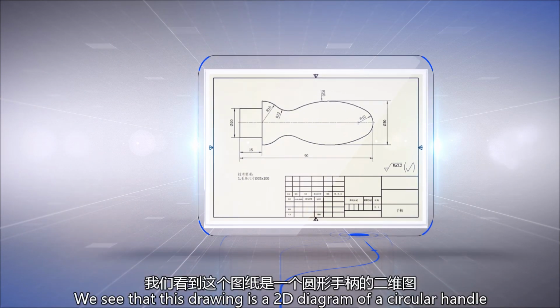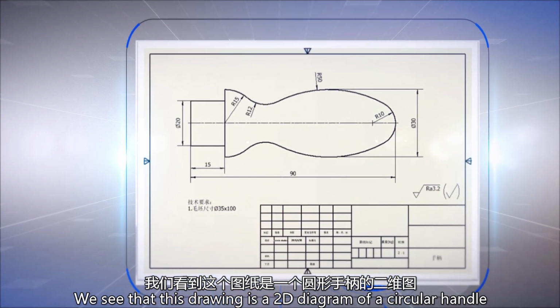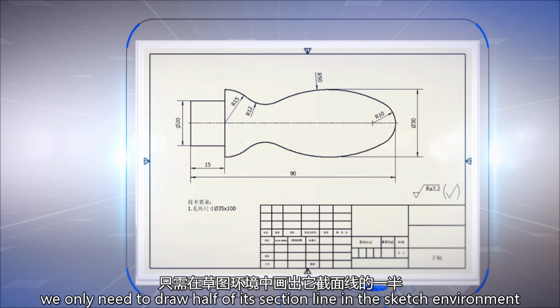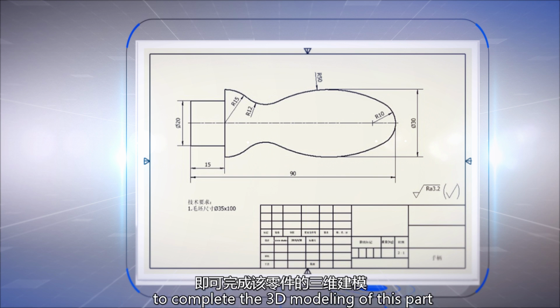Page 2 of the PPT. We see that this drawing is a 2D diagram of a circular handle. So, it's an axisymmetric feature. When performing 3D modeling of this part, we only need to draw half of its section line in the sketch environment, and then perform a rotational modeling to complete the 3D modeling of this part.